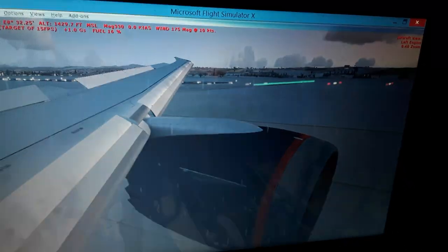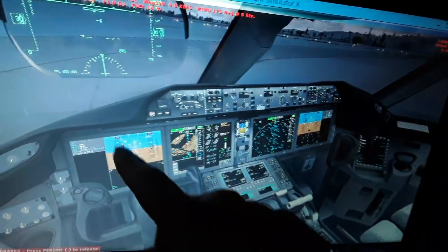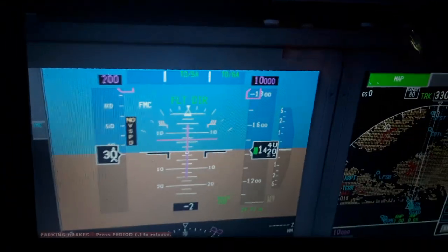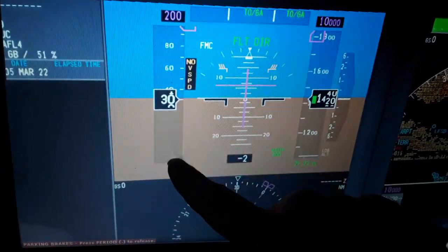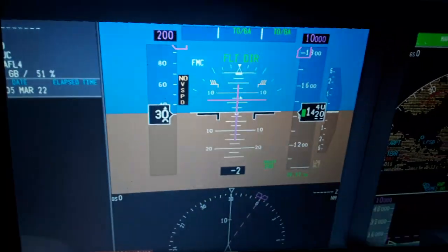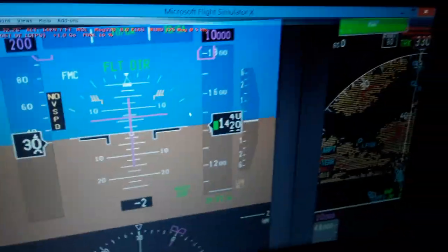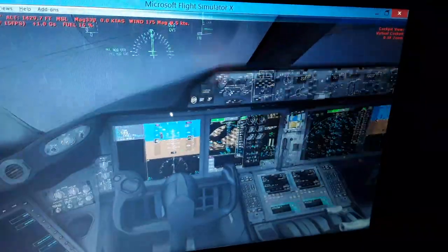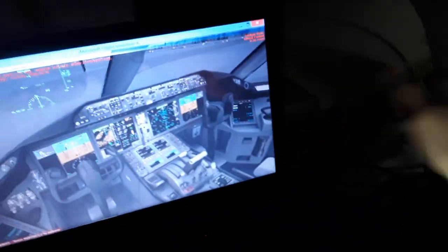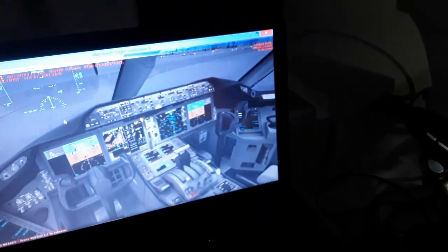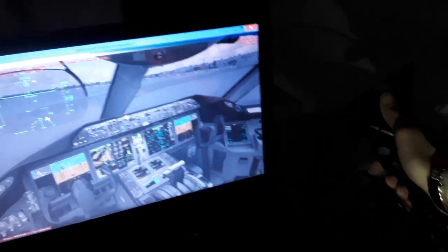So we need to pay attention over here in the primary flight display. You see the airspeed indicated. When we fly, we're gonna see the stall speed displayed with a yellow and red indication just below the airspeed. Also the angle of stall. We need to avoid stalling the wings, so we press the side stick down or the yoke and advance the thrust levers to increase the airspeed. This is the stall avoidance maneuver.